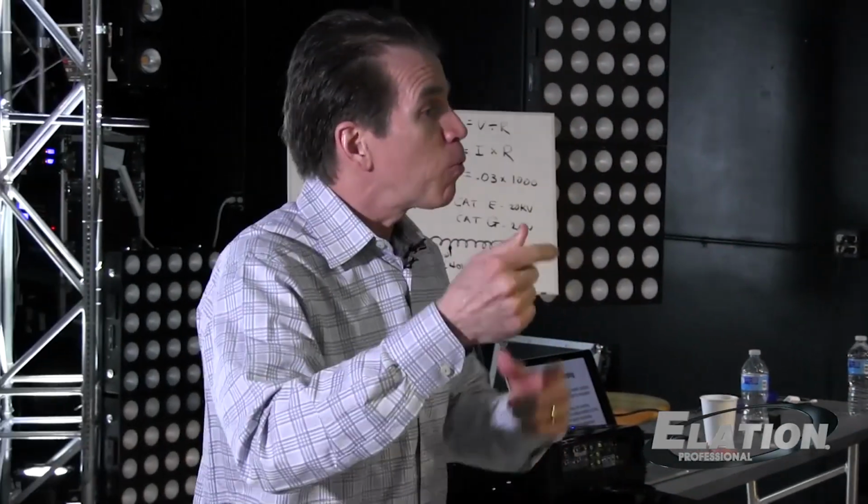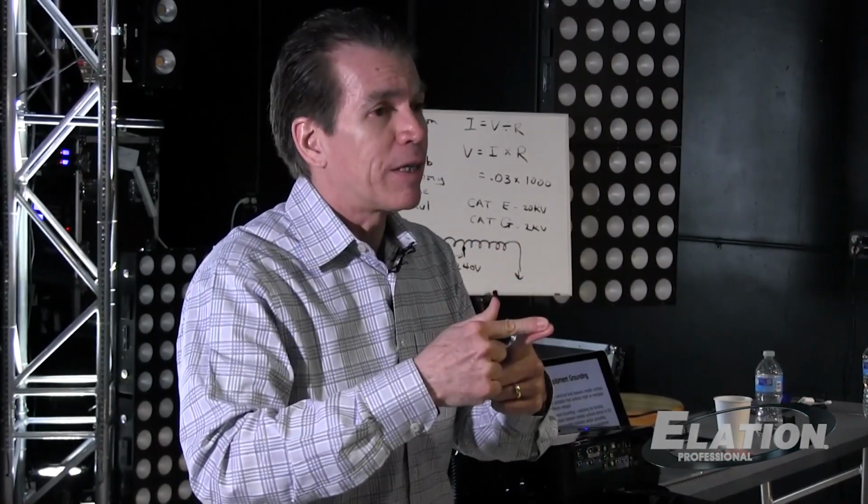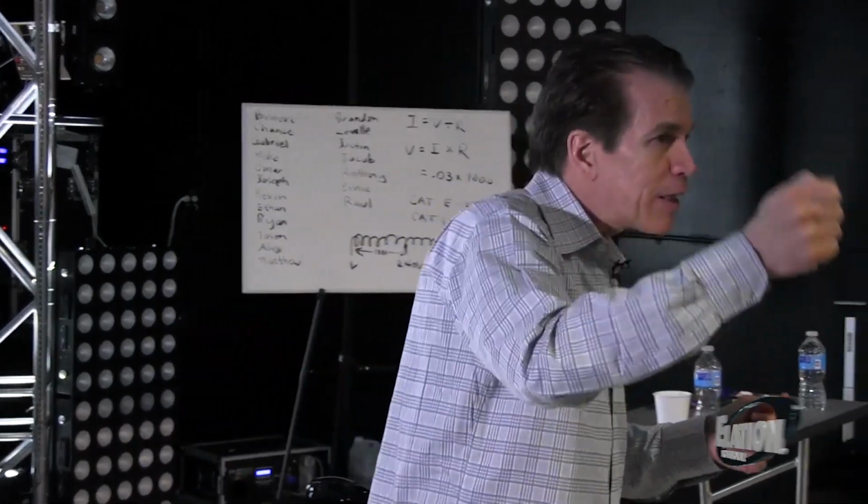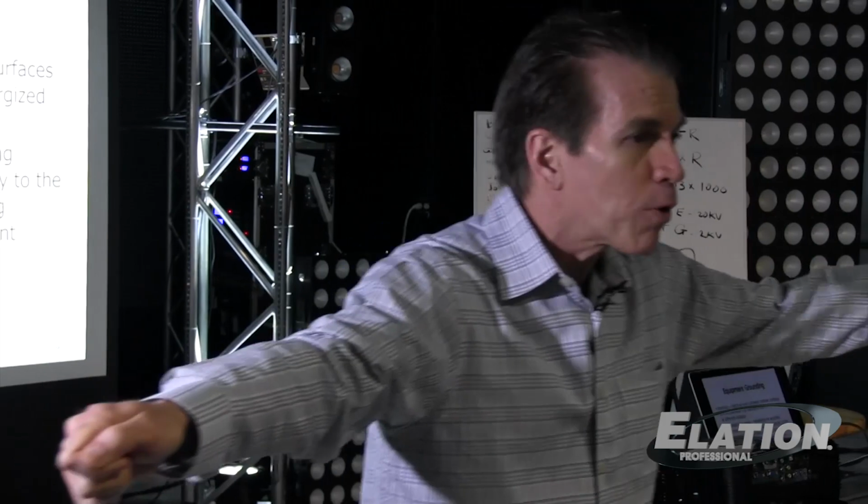But then there's another setting for resistance and for continuity. And a lot of times it'll give you an audible signal when they're connected, when they're bonded. So you can put it in continuity mode. You can touch one probe to one piece of metal, the other probe to another piece of metal, and you should hear it beep. If you don't hear it beep, there's something wrong, and you need to remedy that.